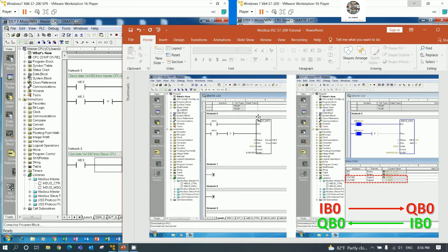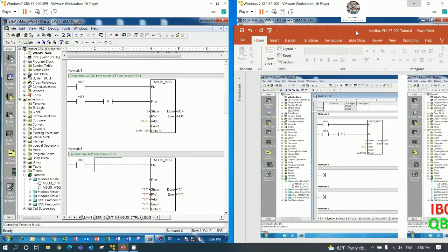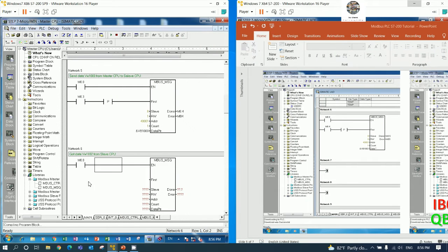Here. And then for this one, the first, right? So first we can use M0.4, right? Here. Can copy and paste. And we need to put the positive edge also, right? So can copy and paste. And for slave address is number 8. Yes. And read write no need, right? Because we got data only.